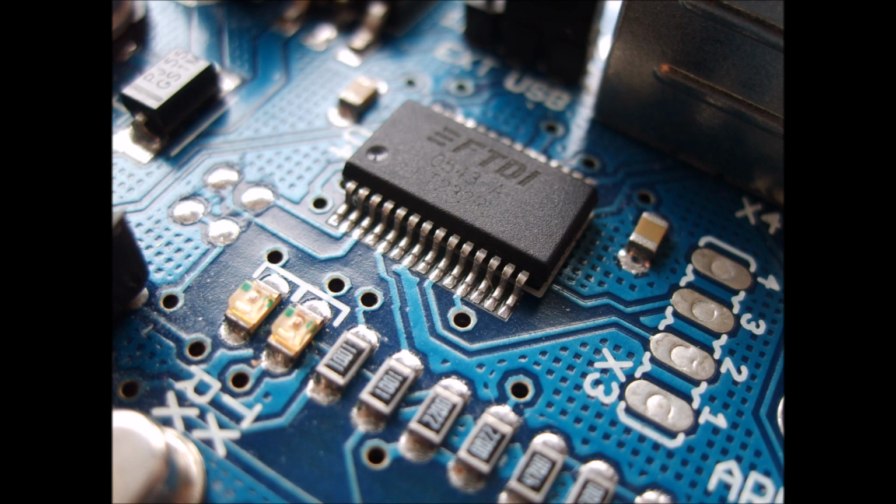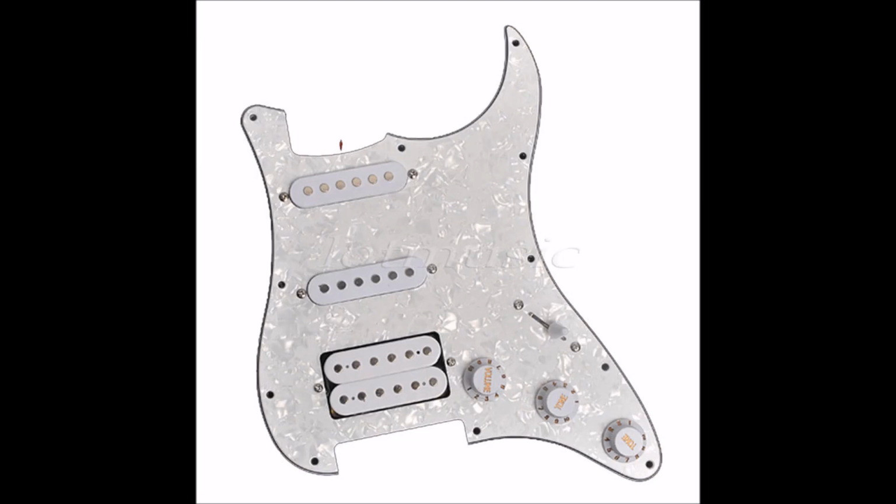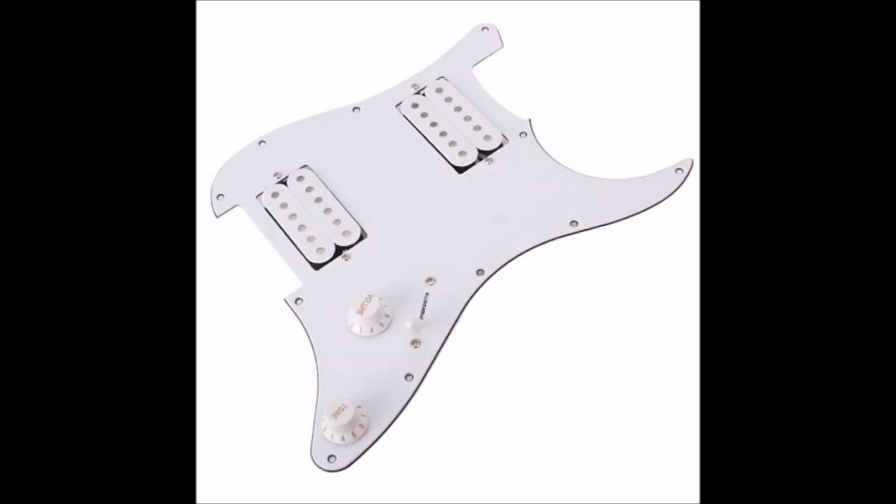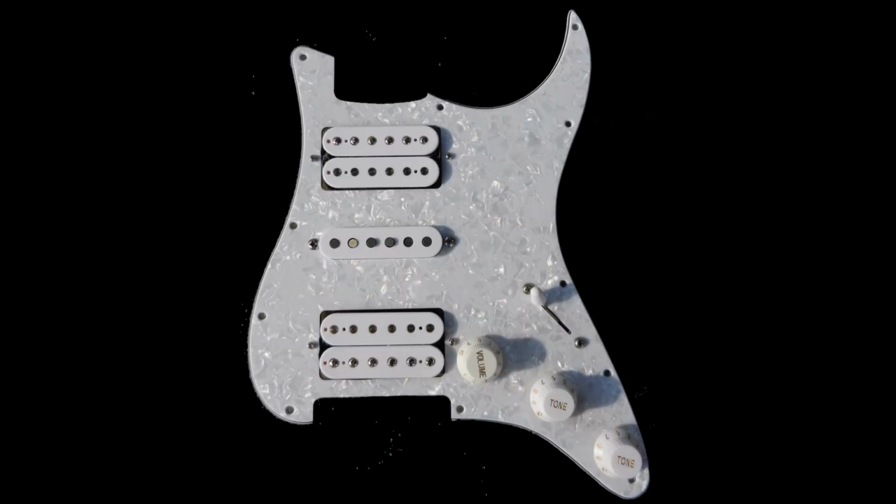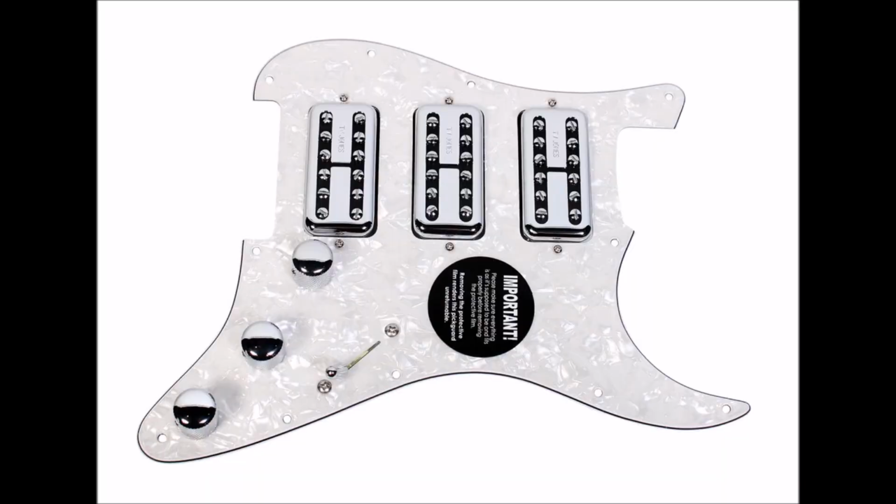This system also easily lends itself as a good basis for a digital design, since the switch operations are essentially binary. The concepts used in the point-to-point system are also applicable in designing the other switch systems. They are also useful in simplifying the circuits, or when expanding them to accommodate humbucker pickups in HSS, HSH, and HHH setups, treating each humbucker as two single coil pickups, to connect all of the coils in complex compound connections.